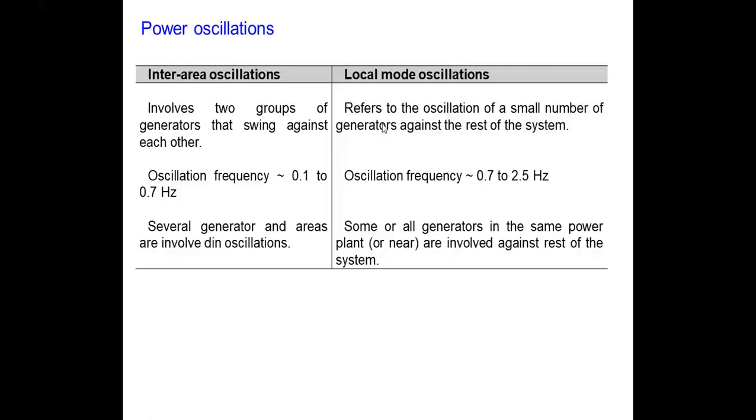That means if you get the delta signal, because the rotor angle you can translate to the voltage angle actually, right? The bus angle. So if you observe the bus angle in the substation, then in that case you will observe that there are some oscillations here. But it will not be observed in the tie line.